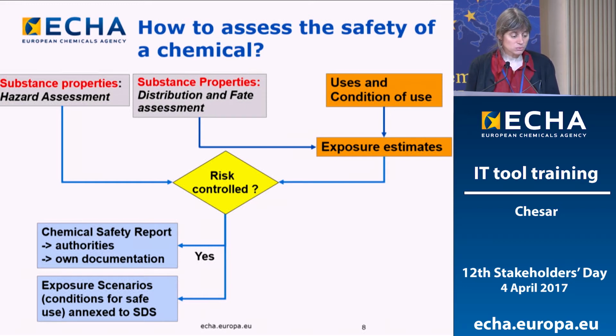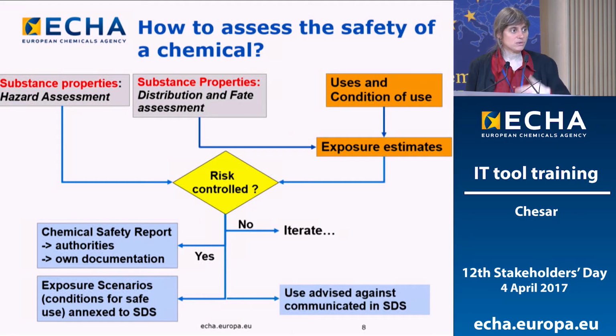If no, two solutions. Either you have to iterate your assessment, so get better information either on the hazard of the substance or on the use and the conditions of use, or you may decide to advise against some of those uses in the SDS, and also provide this information as part of the registration dossier. So this is the basic workflow.